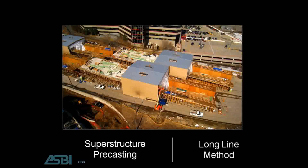To fabricate those segments, the long line method was used. And what you see here are the main lanes of the interstate that were closed because of the other bridge being out of service. A long line basically means the forming system is set up for the entire span, and each segment is cast, very similar to a short line method, but each segment is cast together, and then they're separated to create the individual segments.